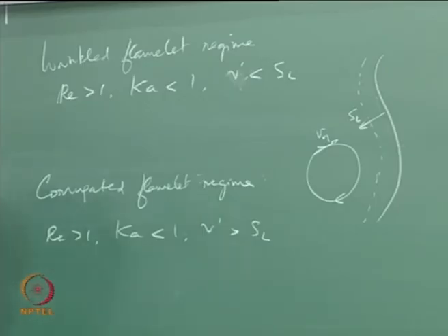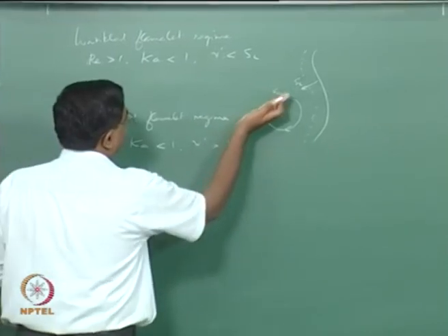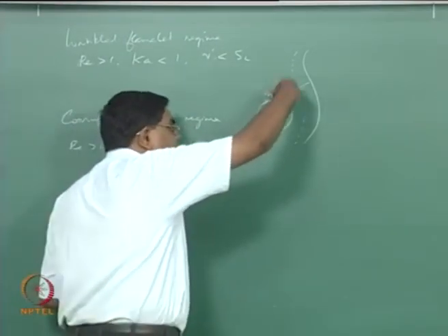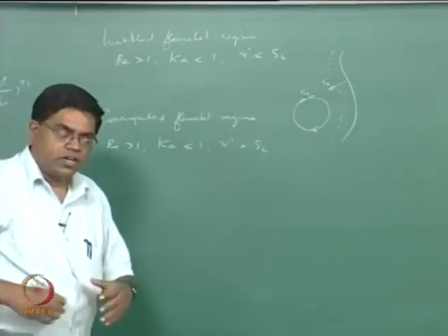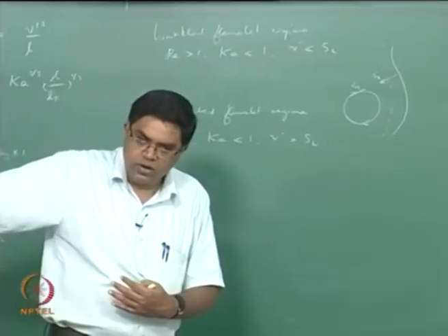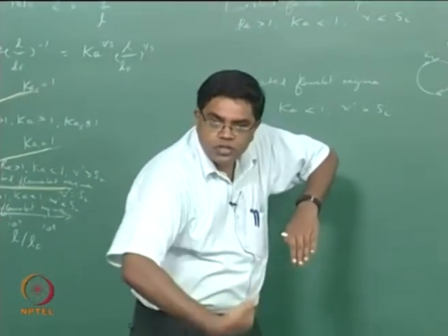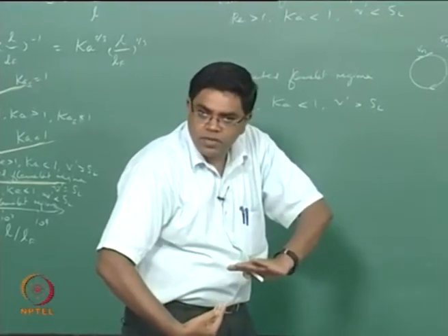The velocity here is going to be large, and correspondingly the flame has to give way. That's how the flame always tries to do things. When the flow is locally large, it gives way by inclining itself to the flow such that only a component of the flow direction is balanced by the flame speed.